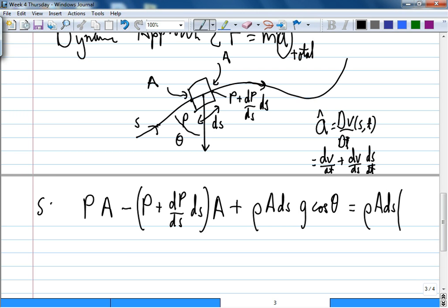But if the fluid is accelerating along the streamline, in other words, here is one speed and down here is a different speed, then this term is positive. There's still spatial acceleration. So in time there's no change, normally we do steady state, so in time, 0.